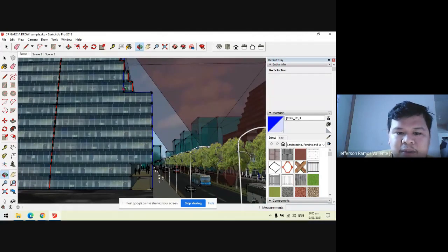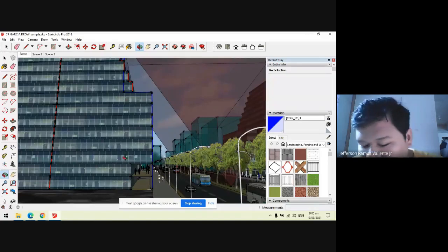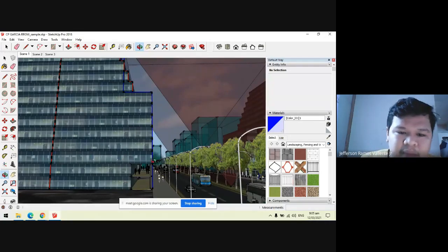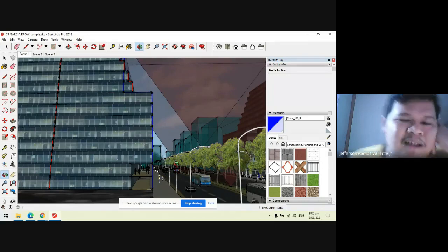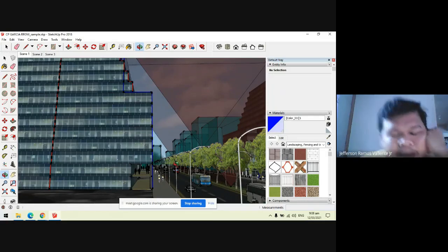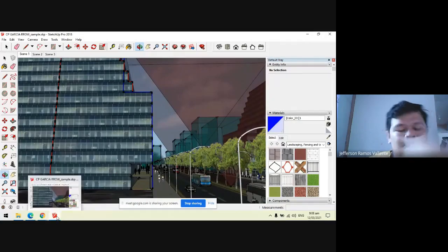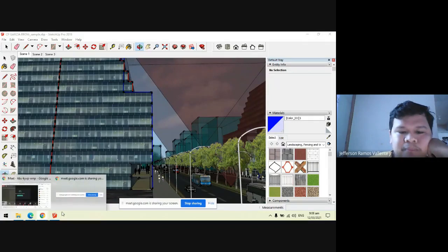So, if you start from there, aside, no need for tapering. But if it occupies the property line above 8 stories, you have to taper too. Okay, that's a person's right to see the road. Okay? So, let's consider this in our designs when you design later the doll house and tower, so that each occupant of that building will have a view of the road or whichever open area that is accessible. It can be a waterway, it can be a forest.